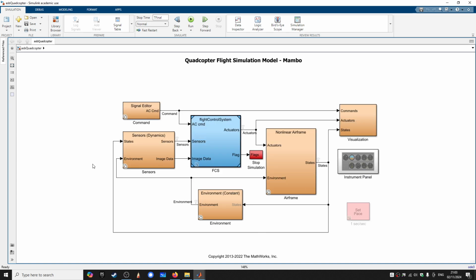I have basically modified the original project files, and the reason is that normally we have our desired trajectories in this block here called command, but when we run hardware tests, only this blue block is uploaded to the actual hardware. So we cannot run a hardware test without the trajectory. What I've done is add the trajectory inside here.